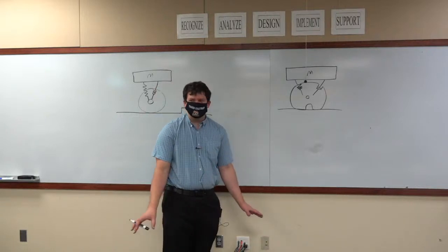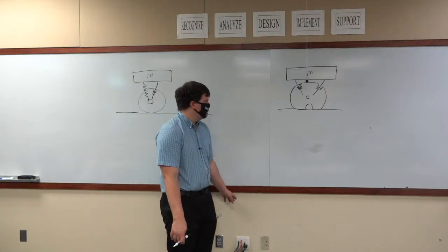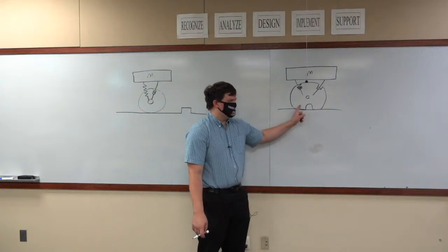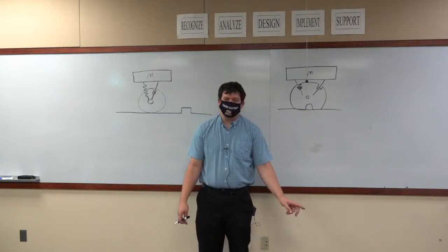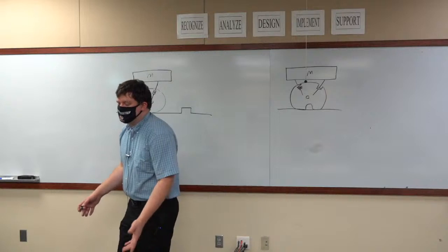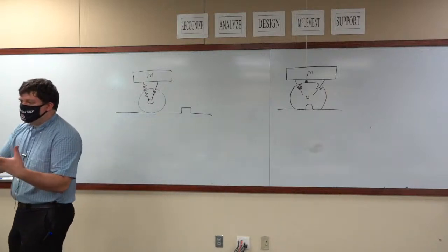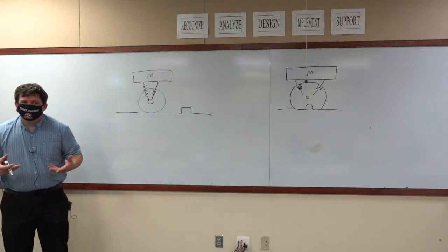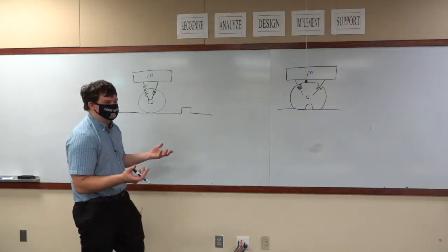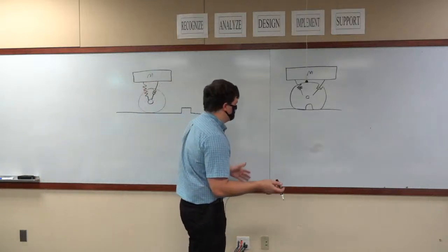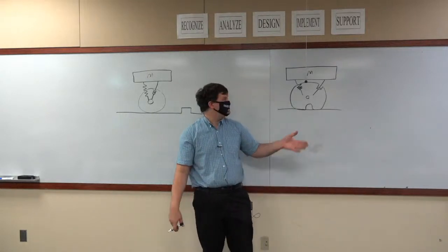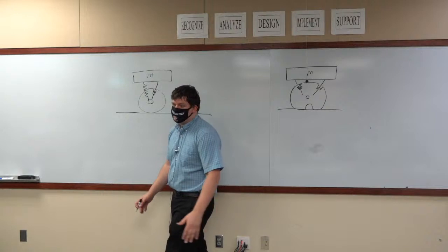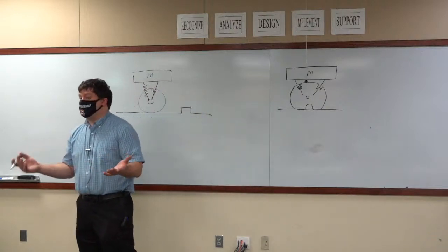In a very, very simple vehicle model, we can assume that any viscous damping that is caused by the tire running over this is pretty much negligible. Yes, it will cause the air in the tire to move a little bit, but it's really not going to cause the air in the tire to move a ton. We're going to assume that. Okay? We're also going to assume that this tire is pretty lightweight compared to the vehicle. So you can assume that the tire itself has no mass.